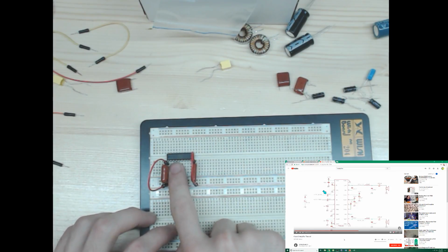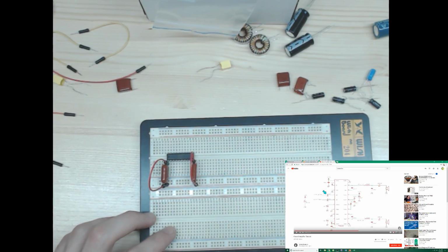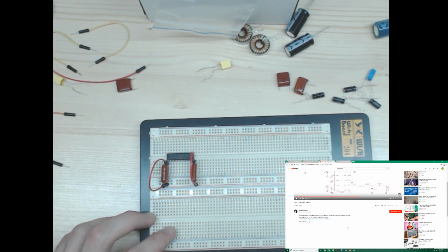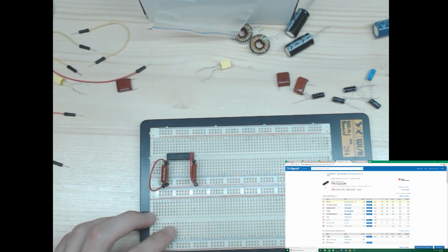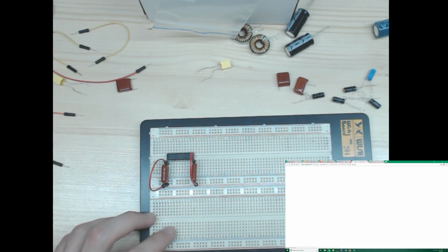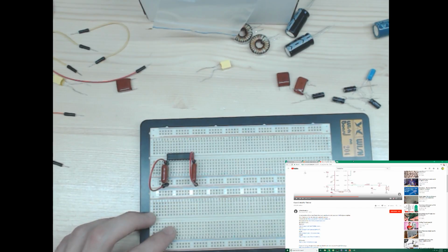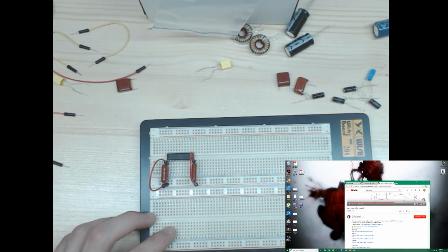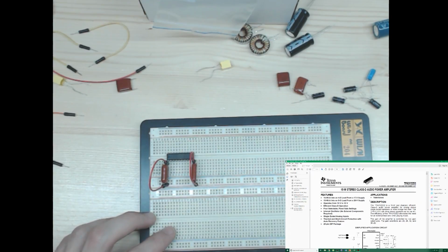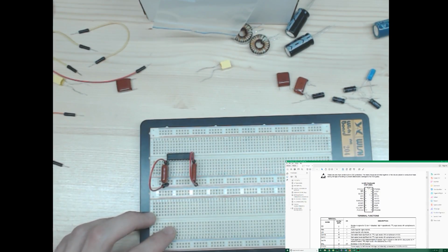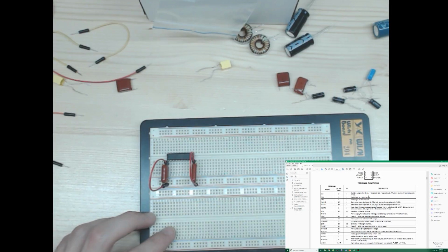The pin right after is SD. SD, if we look at the data sheet of this IC, which I have on my desktop, SD stands for shutdown signal for IC, low disable, high operational, TTL logic levels with compliance to AVCC.